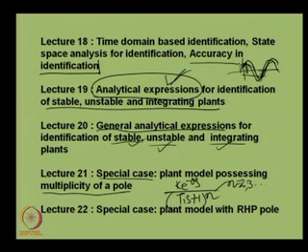So, we shall have a few more special cases on this, when n equals 2, when n equals 3, what should be the analytical expressions and how we can solve the set of analytical expressions using certain nonlinear equation solvers and find the unknowns of the plant model parameters, which are k, theta, T1 and n.